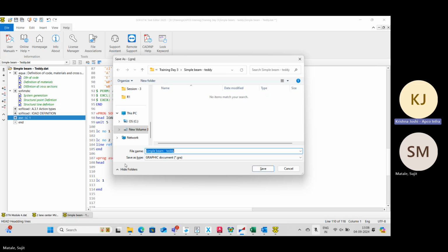To perform eigenvalue analysis, your first period will be very flexible in that case. That will be a problem. In SOFiSTiK, connectivity becomes a problem. Find out the exact location and places you have to define. Exact node connection has to be made. If by mistake the node is not at this place, then it won't connect, and your analysis will have problems, such as load not being transferred to the piles.